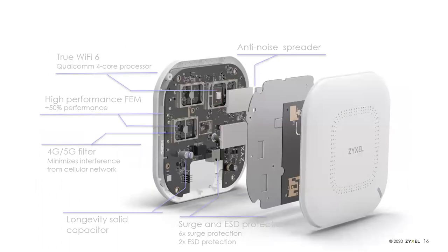And it follows the typical Zyxel design philosophy, which is to build these products basically like a tank. So there's no solid state capacitors to fail. We've got ridiculous amounts of shielding on the PCBA to stop EMI issues. We've got a giant metal plate in the back, which acts as a heat diffuser to pull heat off of the PCBA and the components and vent it out the vent holes on the top there. Heat fatigue is the number one cause of failure in a solid state device like this, so that helps solve that.